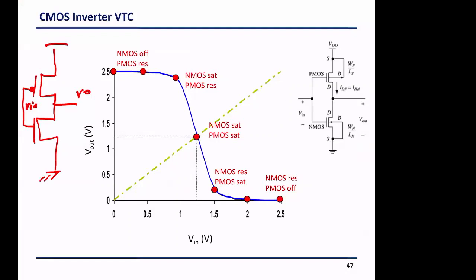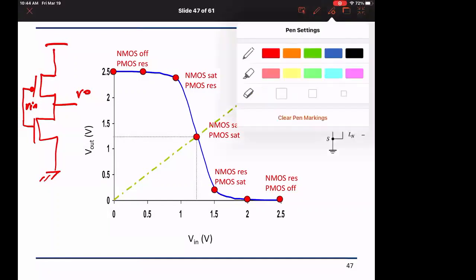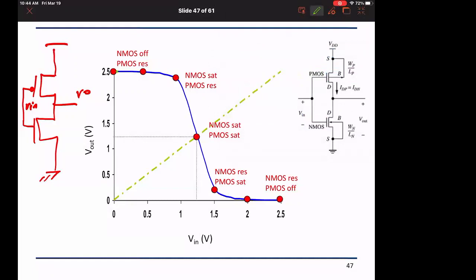So let us see. Let's look at the output. One rule of thumb in this circuit is that when I start with VO high, then this is large, and the VDD minus VO for the PMOS is really small. This is very important for us to remember.